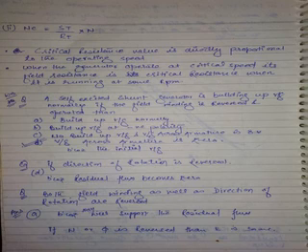You will get a point. So you will make this value. What is the resistance you will get? Here you will get something. Finally you come here and what is the resistance? You carefully examine. It is nothing but the shunt field resistance line only. Yes or no? So RC is nothing but RSH when the machine runs at critical speed.